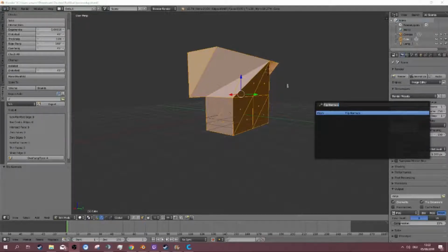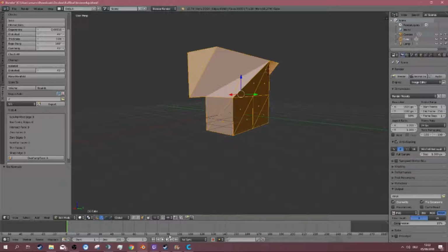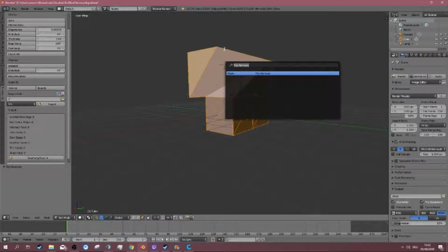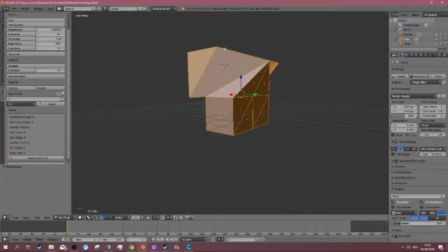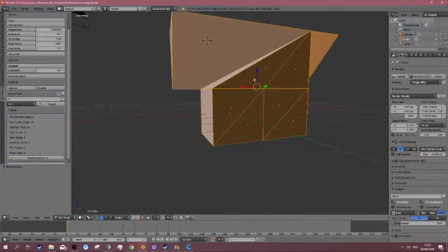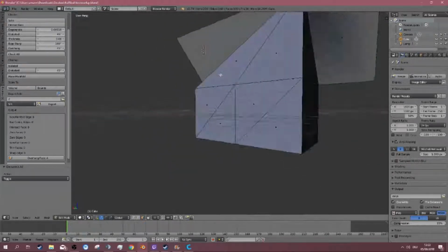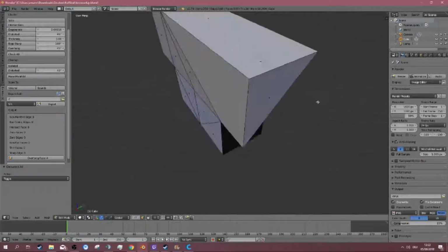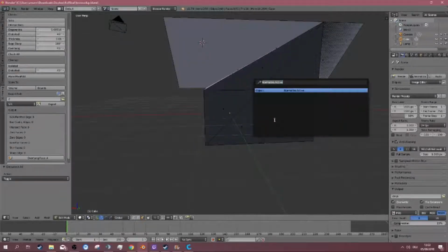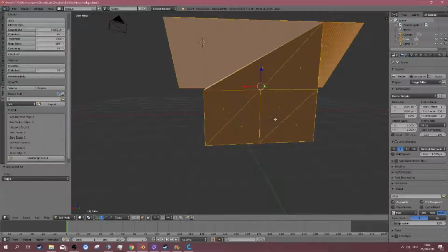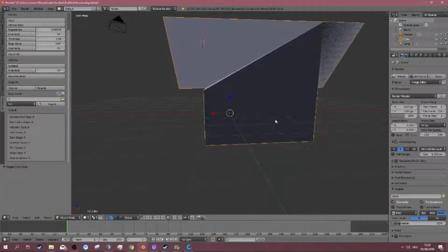You just flip them around. For the normals, you hit spacebar and you just press normalize active. So it flips all into the same in or out. So now everything's out here. And when I hit space and go on normalize active, oh, you need to mark it, then you flip it the other way around again.